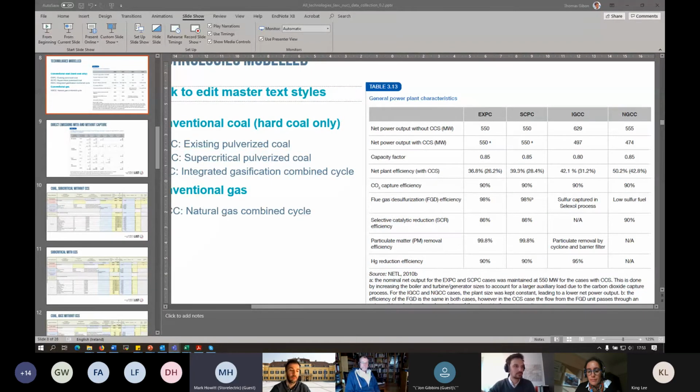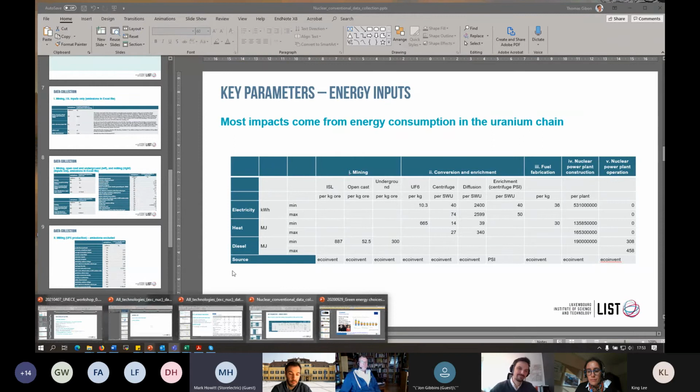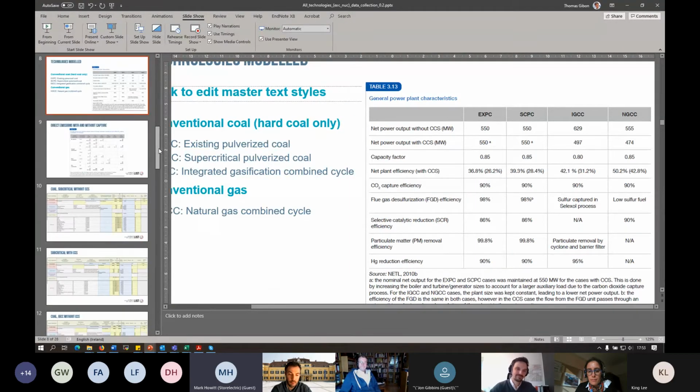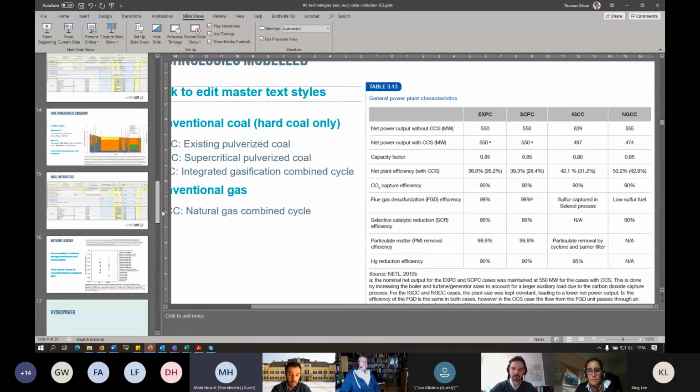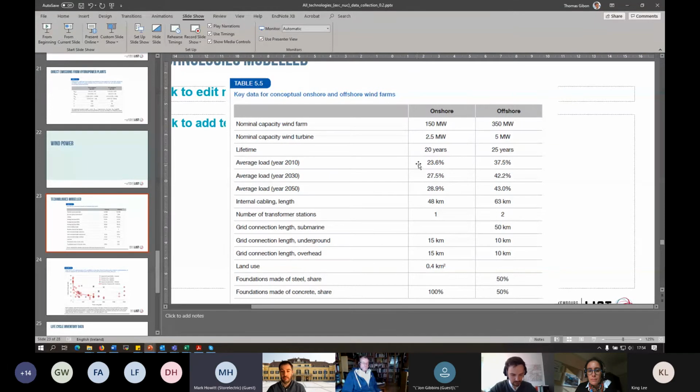One of them is about nuclear power stations. That's in your modelling. A nuclear power station delivers baseload power. Renewable energy delivers intermittent power. So to get intermittent into baseload, you need large-scale, long-duration storage, but you also need 3 gigawatts of wind plus that storage offshore to make 1 gigawatt of nuclear, or 4 gigawatts of onshore wind to make 1 gigawatt of nuclear, or 6 to 10 gigawatts of solar plus that storage to make 1 gigawatt of nuclear. That's one issue. Another issue is the land usage, because you've got an energy density per square kilometer of about 64 megawatts of wind per square kilometer offshore, about half that for solar or onshore wind, and yet nuclear you've got about 5 gigawatts per square kilometer. So that's one issue on nuclear.